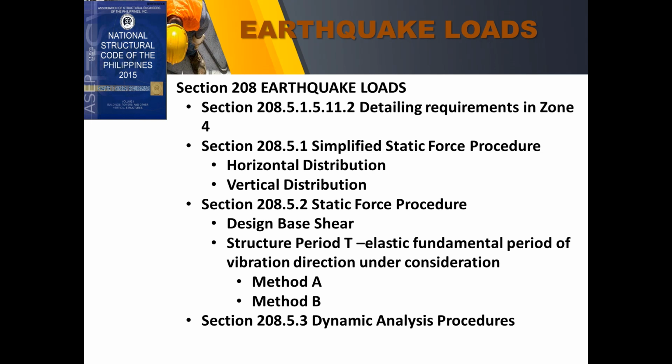We need to compute the design base shear. So actually, static force procedure is commonly taught in the academy. We have the structure period T, the elastic fundamental period of vibration under consideration. So the computation could be method A or method B. And then here, the dynamic analysis procedures. And nowadays, in engineering, performance-based design is also advocated.